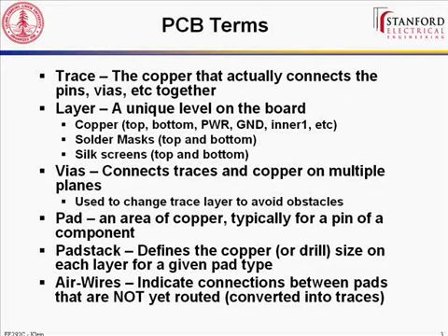Now, different fab companies have different tolerances for all of these things, and everything that's on the next screen. So there's something called solder mask swell, which is kind of how much it will expand and then impinge upon that pad itself. So there'll be some spacing you need to have to keep the solder mask even further away than the pad to guarantee it doesn't get covered. But if you look at the development board that you all had, if you look closely, you can see the very fine line between where the green ends and where the actual silver of the pad begins. So that's the difference between the solder mask and the pad itself.